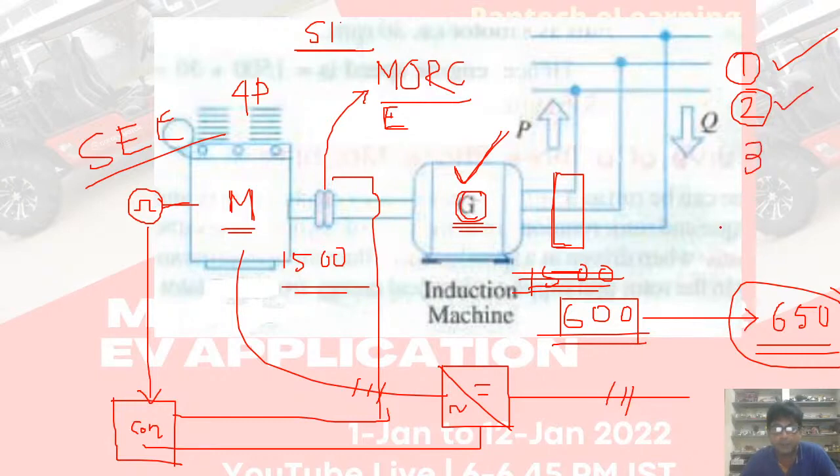Then third, you make the control in such a way that once the speed of this motor reaches 600, then you start this motor which will be driving the generator, also at 600. Once both machine speeds become 600, then you engage this clutch. So my synchronization is over.